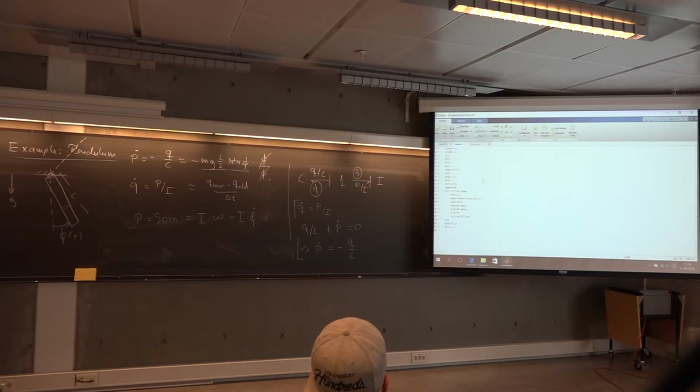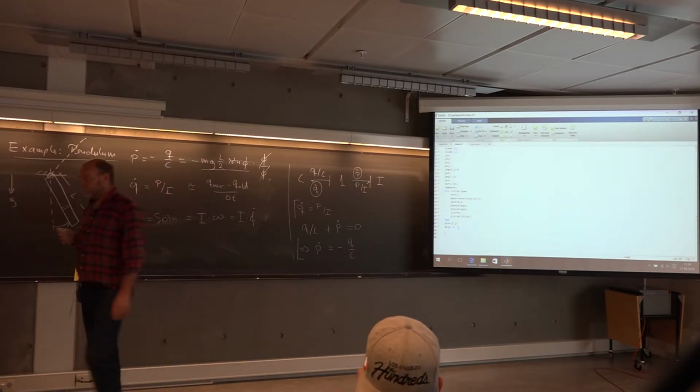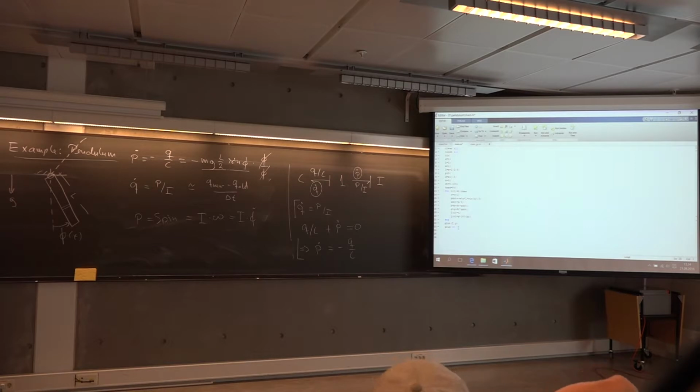Well, we have to stop using a first order method, of course. Let's see, now we are back to the one where we started, yes. So let's try something else here. Instead of using first order Euler, let's start using an ODE solver instead. ODE solver, what was the syntax? That was time and y equals, on the other side, ODE 45 of, and then we need a function.